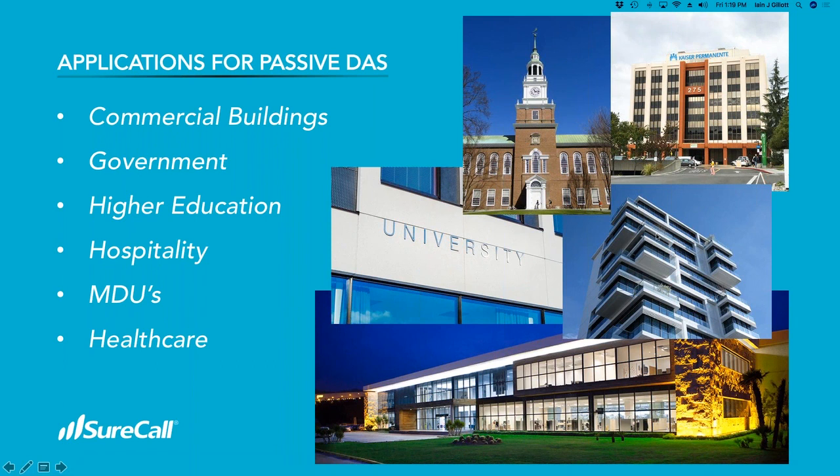And again, if you look at something like the old clock tower building there, which looks like an old university, you would think that would be a horrible RF environment. Actually, sometimes brick, depending on the age of it, can be pretty good. Again, lots of windows, but you'll notice it's got a copper roof on it. Metal roofs are really bad for penetrating RF. So the variation you get with those buildings is very important.